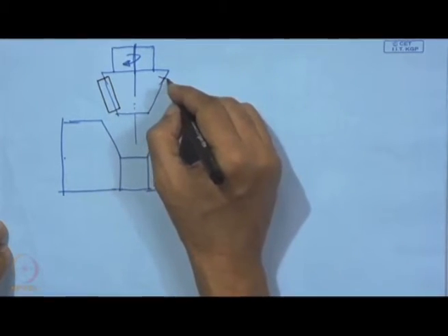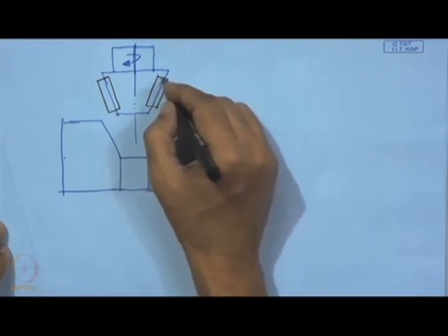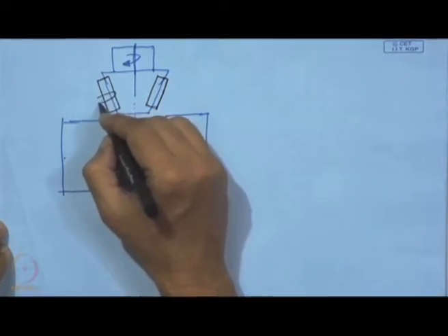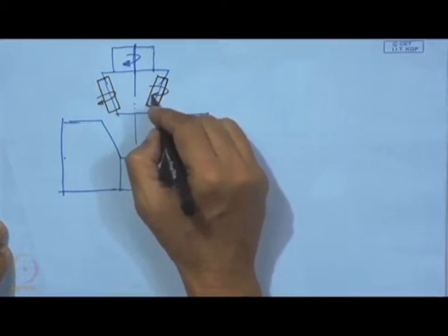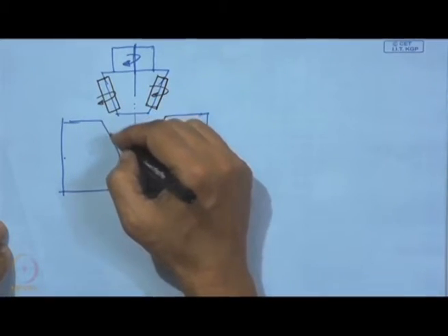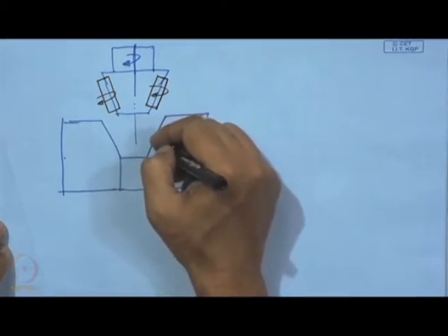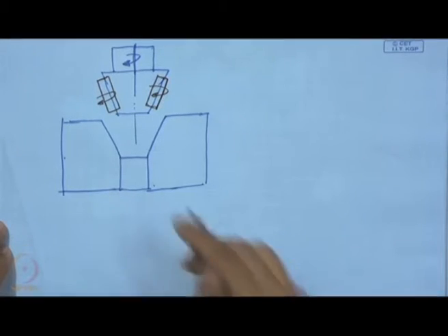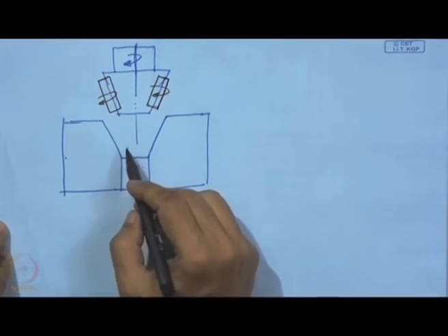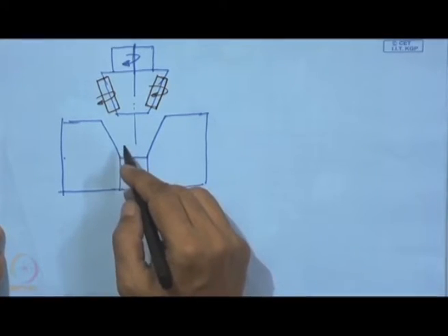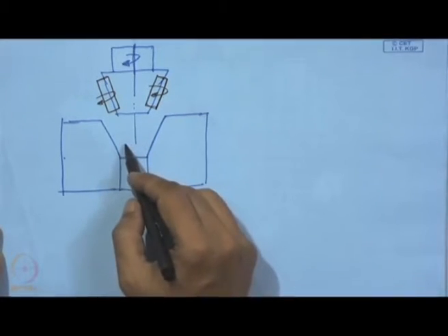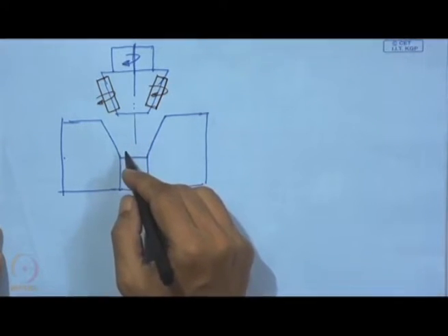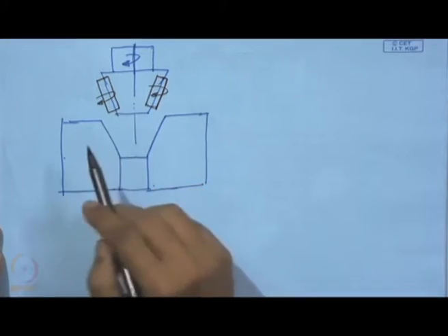So, it is a taper surface, and geometrically they must match and fit properly. This roller will spin, and this is also going to spin, and in that case we have roller burnishing over this entire conical surface. The whole idea here is to improve the fatigue character, or the resistance to fatigue, and that resistance to fatigue can be remarkably improved by this roller burnishing action.